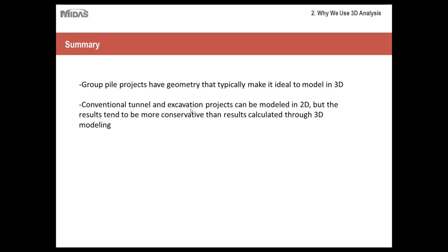And then conventional tunnel and excavation projects can be modeled in 2D. However, the results tend to be more conservative than results calculated through 3D modeling. So just keep that in mind. Even though you're saving a lot of time and effort by modeling in 2D, ultimately the results that you get will be more conservative than a 3D model.